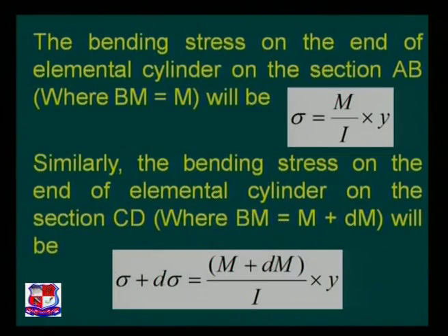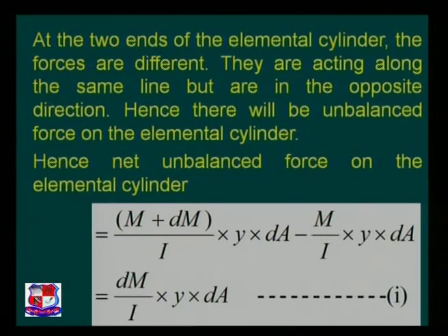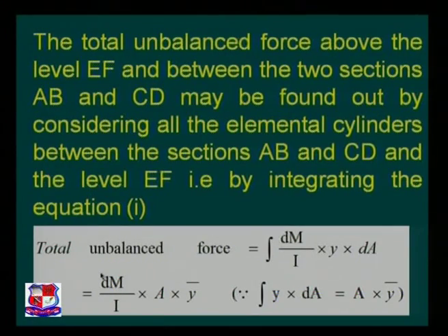Now we have to integrate to obtain it for the whole section. If you want to visualize, this is the net unbalanced force on the elemental cylinder, dM by I into y into dA, and to obtain the total unbalanced force we integrate this equation. That is, the total unbalanced force is equal to the integration of dM by I into y into dA.